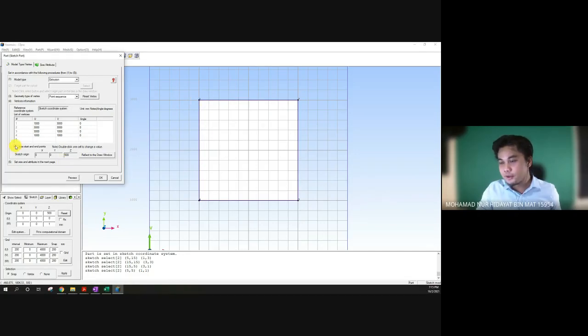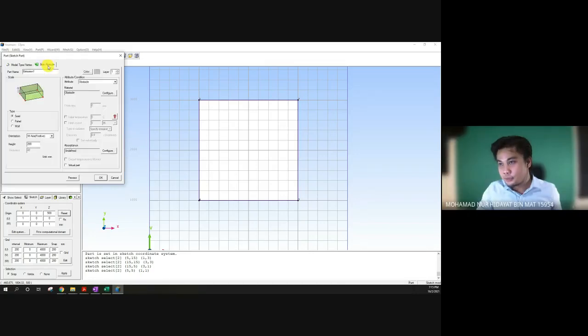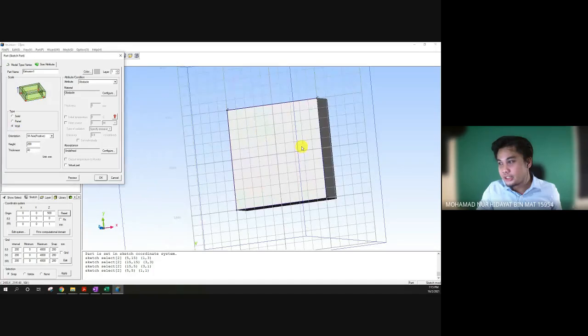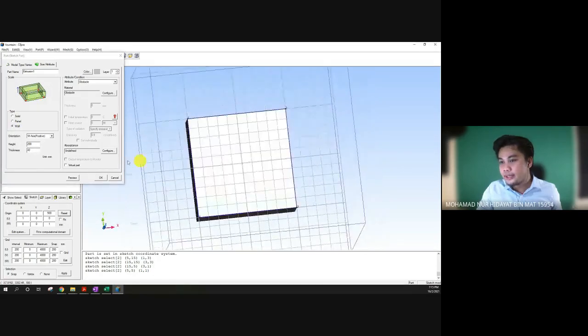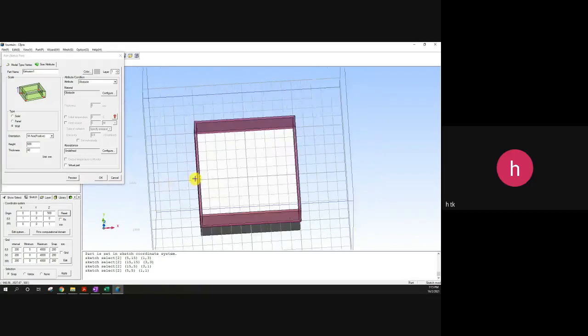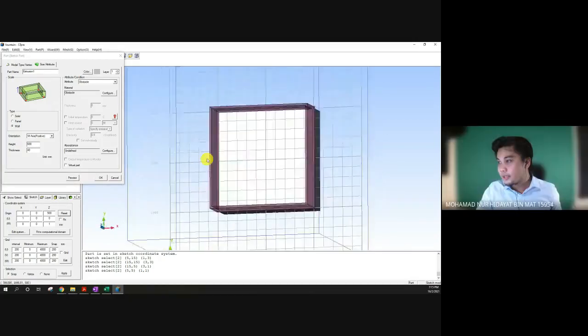And then go to the size or attribute and change the type to be the wall. Okay, can you see this? This is the solid. When you select the wall, it changes. It becomes the wall. And then what is the wall height? Maybe 700 or 600. You can preview. Can you see? Yes, you can preview your wall.